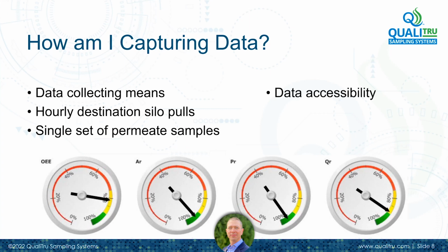And where is data stored? Is it a spreadsheet for later use? Is it kept on clipboards? Is there a way to have lab samples tagged so that it meshes with a database of inline process measurements? Do we have sharp enough data to provide healthy and timely triggers and warnings to predict issues in advance so that we can take action? And can there be a laboratory information management system kept up to house all of this really solid data?